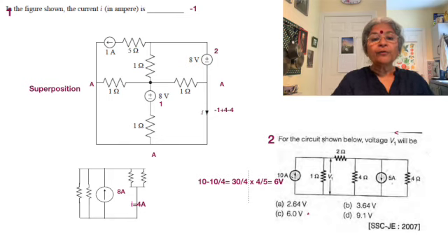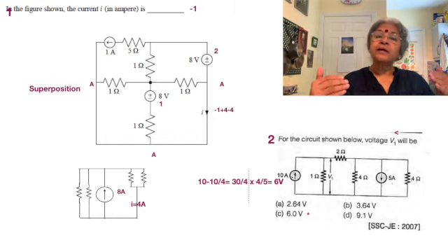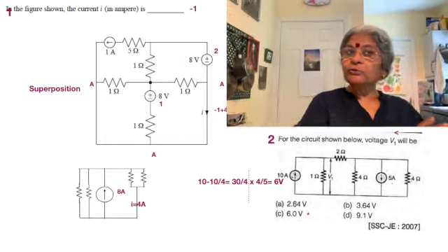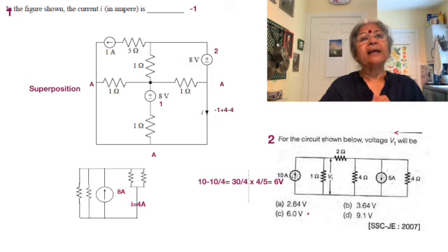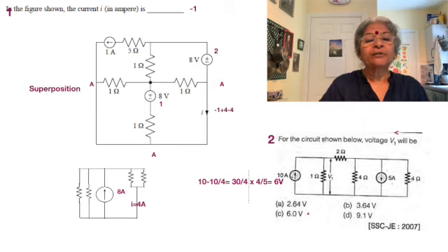If you observe the middle 8 volt source, the picture is similar. There's a 1 ohm resistor in series. Thereafter, the current diverges through 3 equal paths, and 2 paths are connected together at AA dash for the current to flow. And these currents are going to flow in opposite directions. Here also you can use source transformation, and here also you see that there is an equal amount of current, but flowing between A and A in opposite direction because of the direction sense of the 2 voltage sources. So they cancel each other, and so the value is equal to 1 amp.